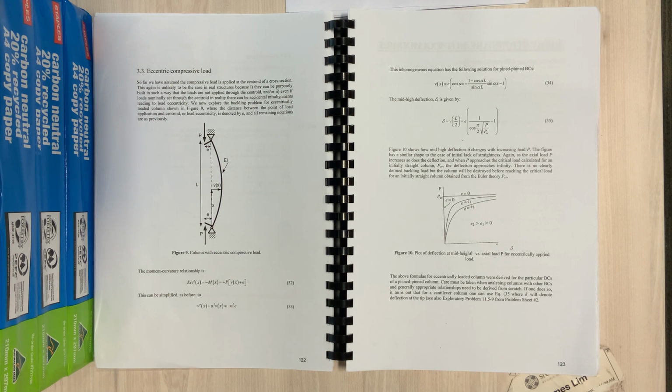So we're basically just going to be lumping everything together. We know that there are geometrical nonlinearities, which may need a laser scanner to help you overcome, to find out the magnitude of the geometrical imperfections. We know that there are material imperfections, and that you can't expect the material properties of the section to be completely the same. There's always going to be some natural variation in them.